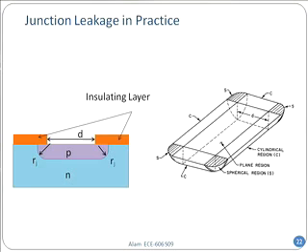Generally if you have a sphere, then you have a certain electric field. But the lightning rod on the top of many homes has a very asymmetrical shape, right? It's very long and very sharp because sharp points have high electric field. So although you did your design on the one-dimensional thing that I just showed you in the previous one, in the real device, you will have these corners where the electric field will be very high. And in that case, you can have a significant amount of recombination on those points. So one has to be very careful about designing junctions for practical devices.